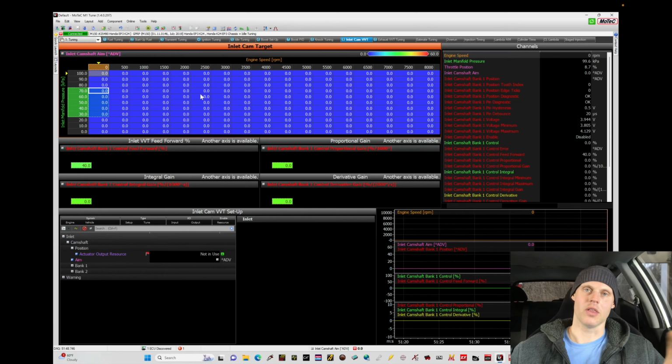So we know the last training module, we sorted out the drive-by-wire control, the idle control. We know the engine can crank, fire, and run and hold its idle. Now we're going to take a look at moving off idle and being able to deal with operating beyond that point. So when we're talking about variable valve timing, we want to zero it out at idle conditions. So between 0 to 1,000 RPM, 100 to 0 kPa within this table, that way I've set the breakpoint scalars, we're going to keep our values here at 0.